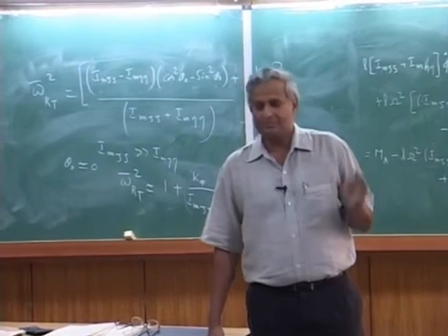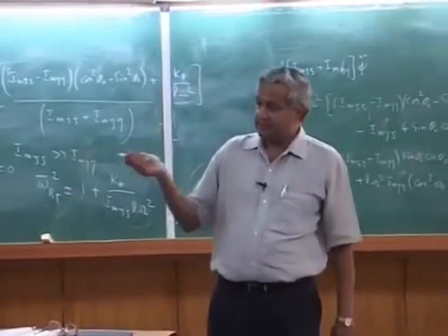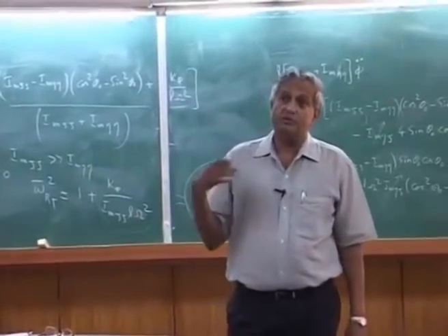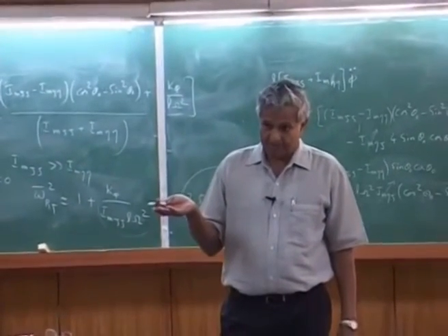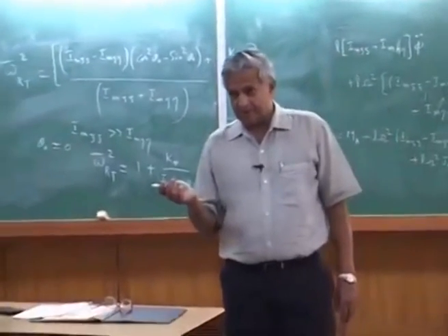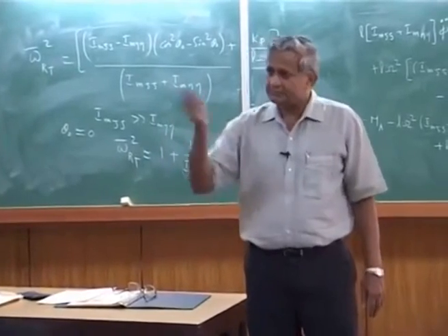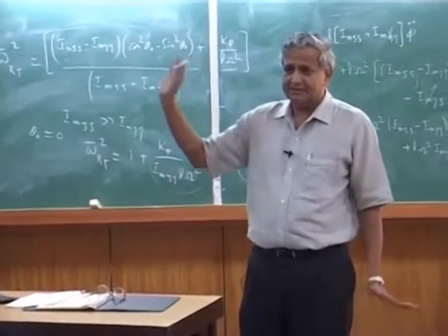Therefore, it's all right. Then in the bending problem, you have an axial, because it's a combined, if you want to treat axial motion, centrifugal force you have to bring it to effect. If you make it as a rigid blade, it is taken care of because you are not bothered about that.